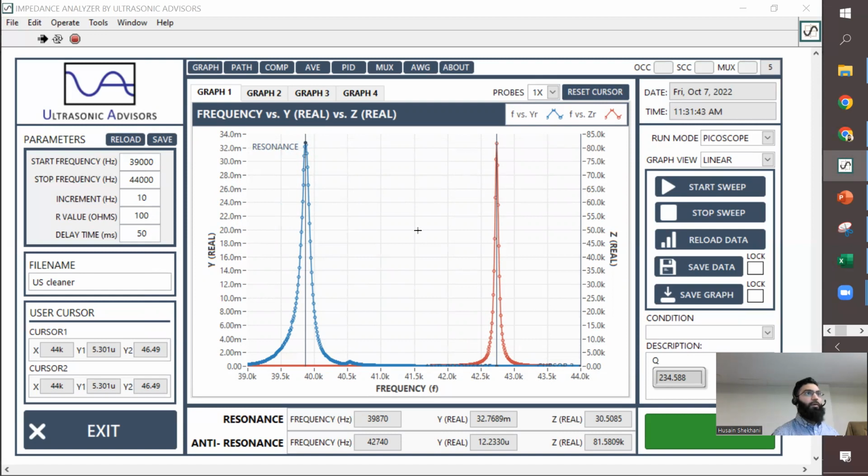Yeah, this is actually the real deal for calculating. Yeah, use it all the time. Yeah, the experts use it all the time. So now everybody's an expert. That's why I'm mentioning this. For ultrasonic cleaners and high Q devices and high coupling devices, there's no need to do this. But if you're going to take away something today, many of you work on maybe higher frequency devices, or you have low coupling factor, low quality factor. This is absolutely vital to use for low quality factor, low coupling factor.